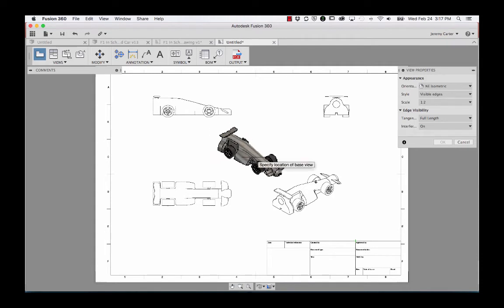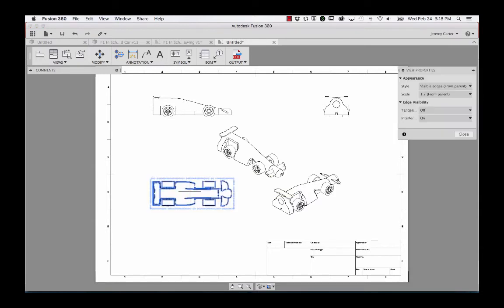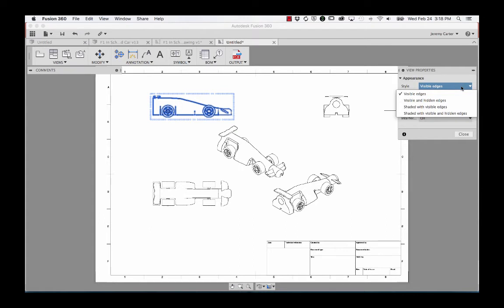Note, what is shown in this tutorial is purely representative of what can be achieved. You will need to research the ISO drawing layout standard for third angle orthographic technical drawing so that you can ensure your drawings comply with the standard. Double-click any of your views to enter the View Properties window to change visibility settings. Shaded gives you a render of your car also.